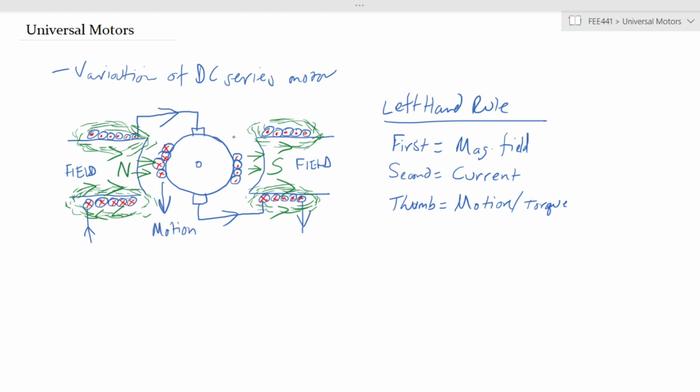And on the opposite side, because you have the current flowing in an opposite direction, the motion will be in that direction, upwards in this particular case. So here you can see, simply by setting up an electrical current through the machine itself, you end up with a torque that will tend to move the conductors around.